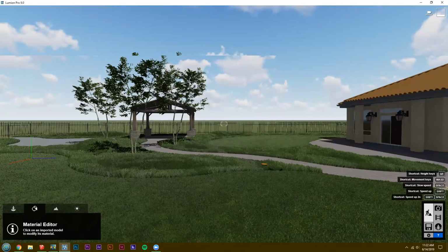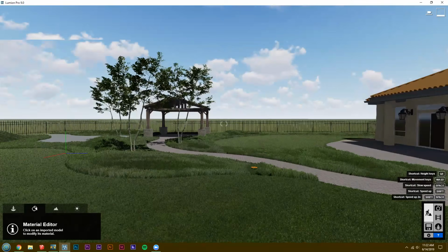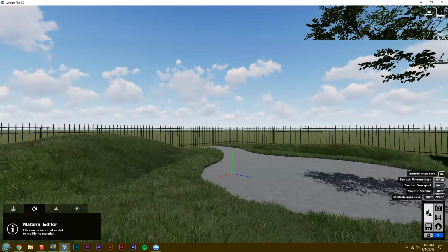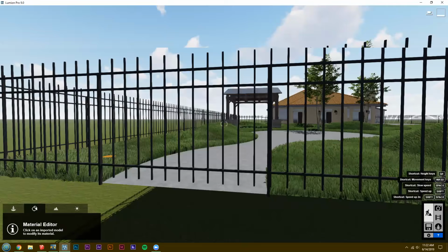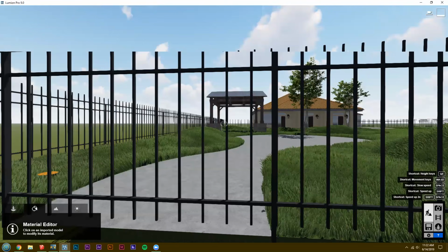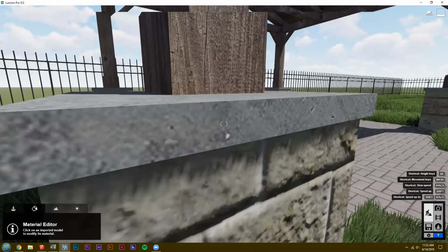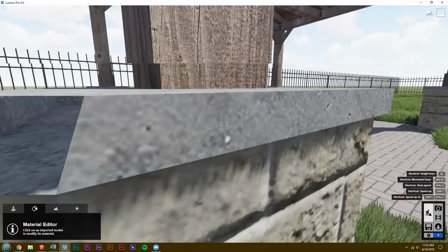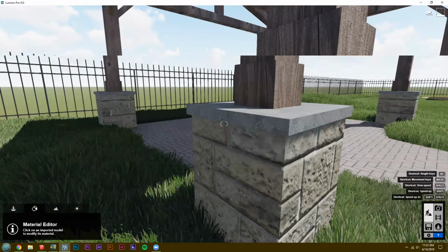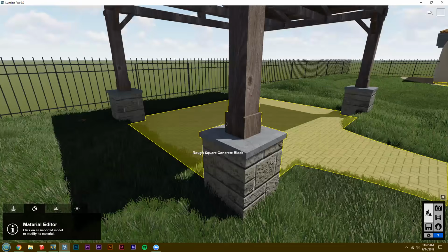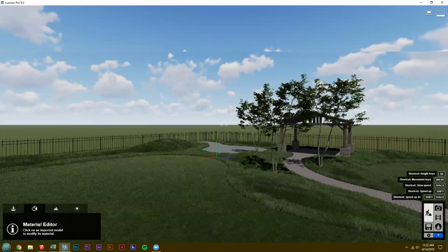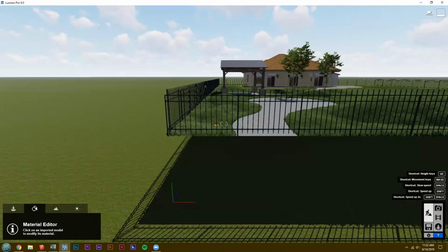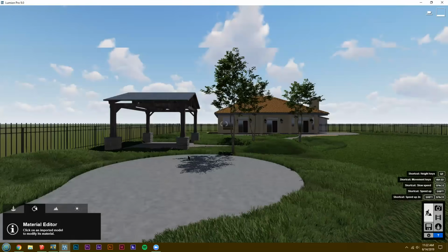And so that's why I also like to put it right near the origin, because if you're pretty far off, then when you zoom into things, it starts clipping. I mean, obviously I'm right in this model, but just being probably like right here, it would start clipping, and it's just difficult to work in. So I always recommend just cleaning up your files and putting them as close to the origin as possible to just make it as easy as possible to work in.